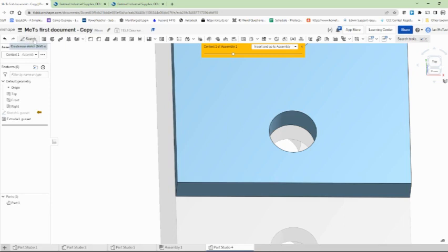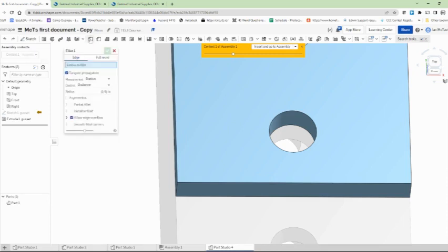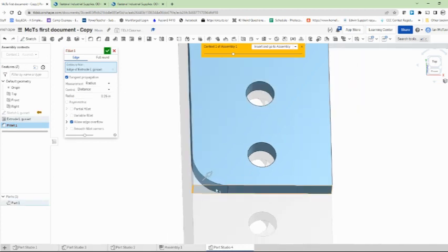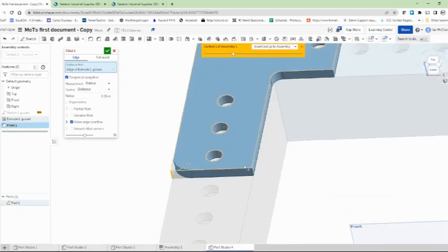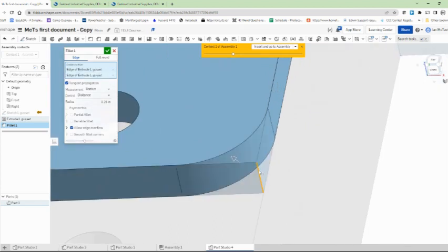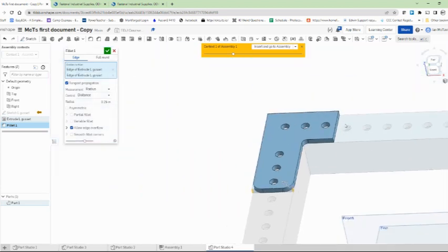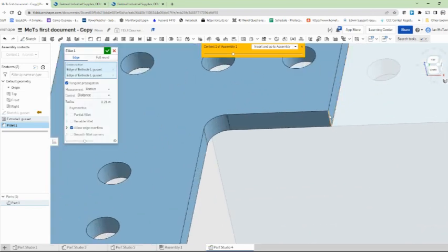So we've already done a fillet in the sketch, but you can also do fillets outside. So this is the fillet tool here. And with the fillet tool, I can select the radius, 1/4 of an inch radius. That's bigger than I need, but it looks nice, so I'm going to stick with it. And then the edges. And so I'm going to zoom in and click that little tiny edge, and you can see there it fillets it. And there we go. So I'm going to fillet these corners.